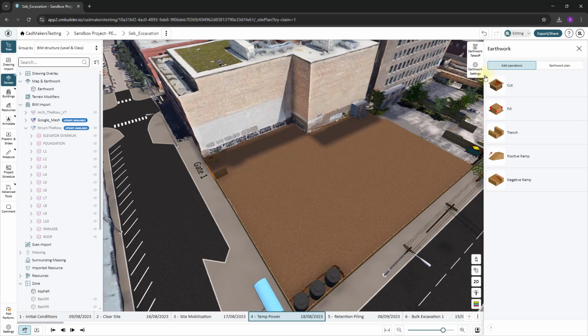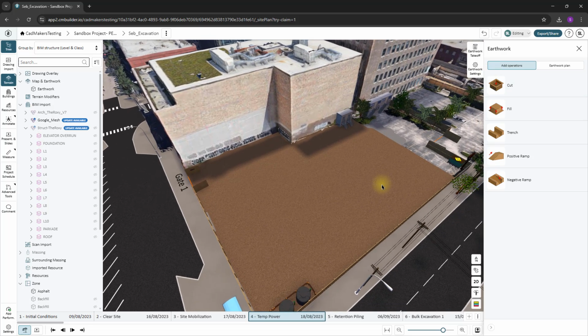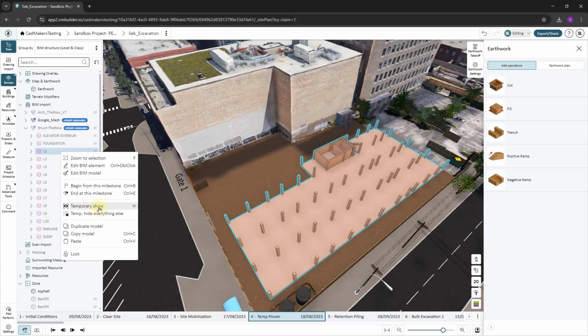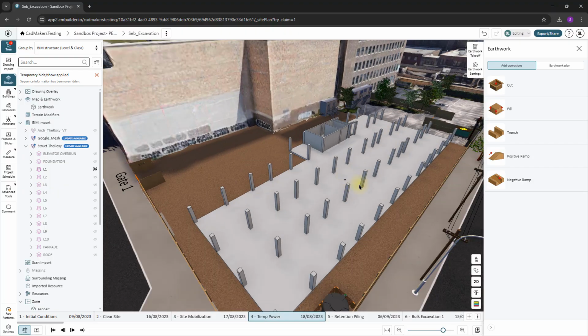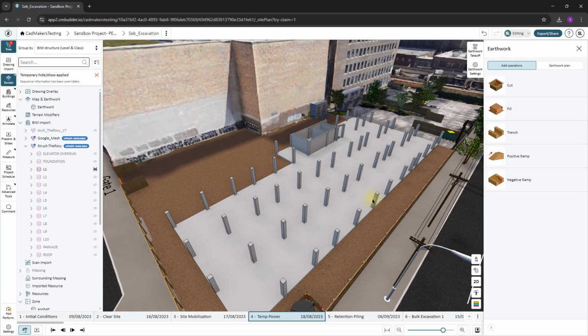As best practice, we suggest importing references like drawings or 3D models to improve the excavation accuracy. You can find additional instructions in our Drawing Overlay and Upload BIM Models tutorial videos. Remember to check the elevation of the default terrain near your site, as we will be using the sea level as reference for some of the operations.